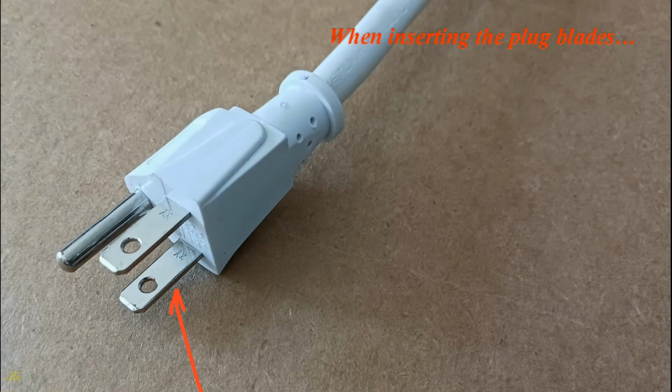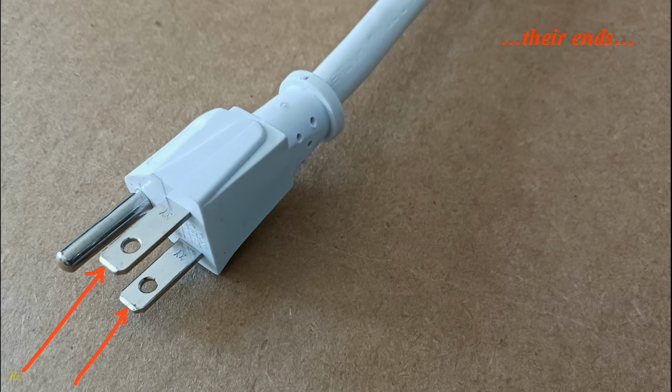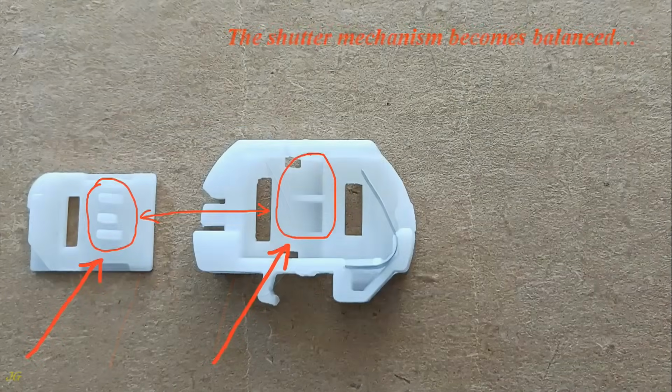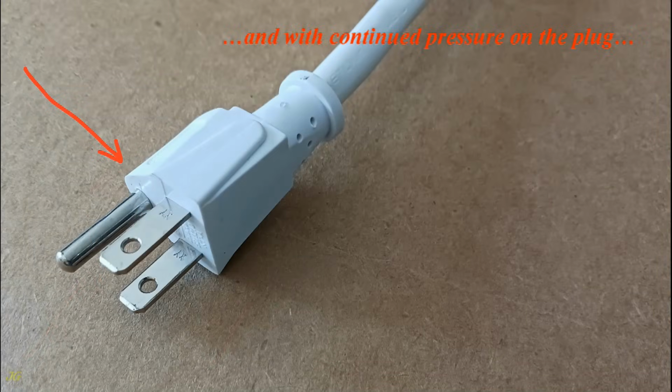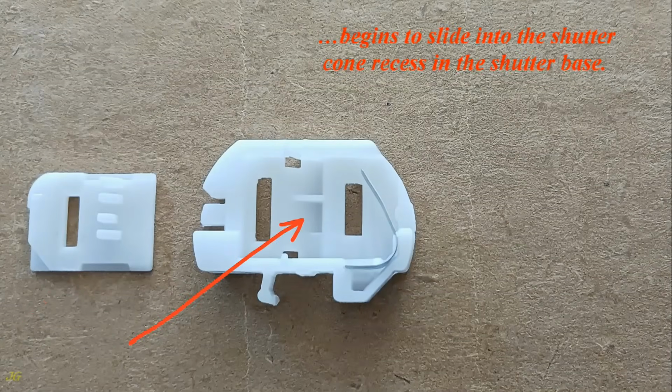When inserting the plug blades into the receptacle slots, their ends press evenly and simultaneously on the shutter. The shutter mechanism becomes balanced, and with continued pressure on the plug, the shutter cone begins to slide into the shutter cone recess in the shutter base.